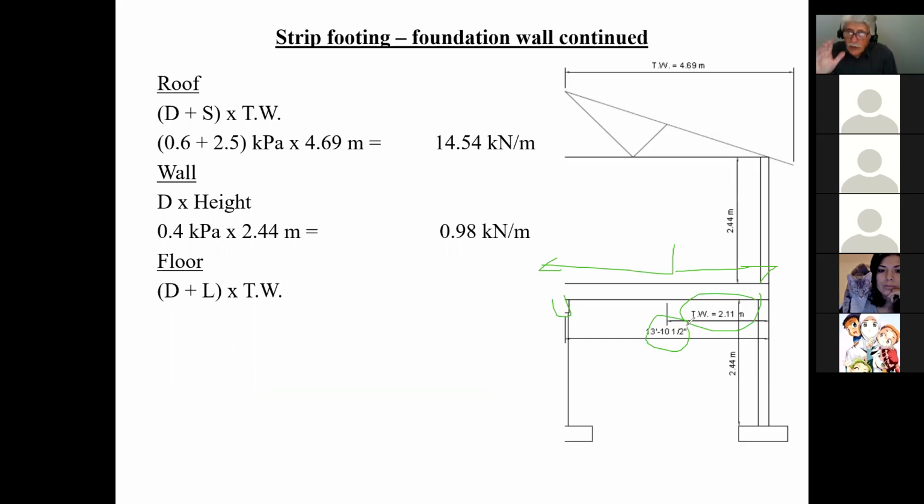That's why, guys, you take your time. Before I do this, believe it or not, I make a sketch of my cross section. I do my geometry first, and then on my geometry I list my materials. From my geometry, I do my list of materials; from my list of materials, I do my loads; from my loads, I then continue. So there's a very systematic way of allowing you to move to the next one. I recommend that if you're going to be doing this for yourselves, get into that practice.